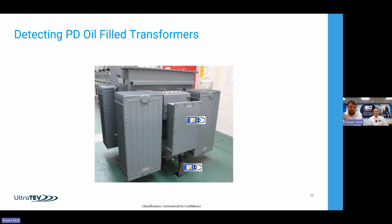So where would you look for PD? Nice and simple on the full transformer. Most things from a PD point of view call back to the cables. And we're able to therefore take measurements on the cable itself and on the cable termination, so the cable box and the outside metalwork, using the TEV, the contact transient earth voltage capacitive sensor in the top of the device.